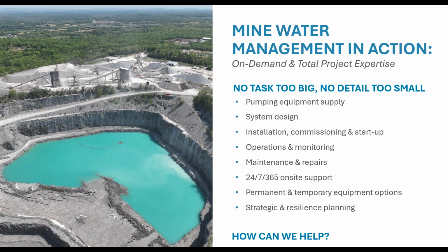Obviously there's going to be an expected flow of water from what your ground surveys might have indicated, but you have to take into consideration a little bit of a safety factor, knowing the weather in your area and the likelihood of any major rainfalls. And also, there is unexpected water underground that could be encountered.